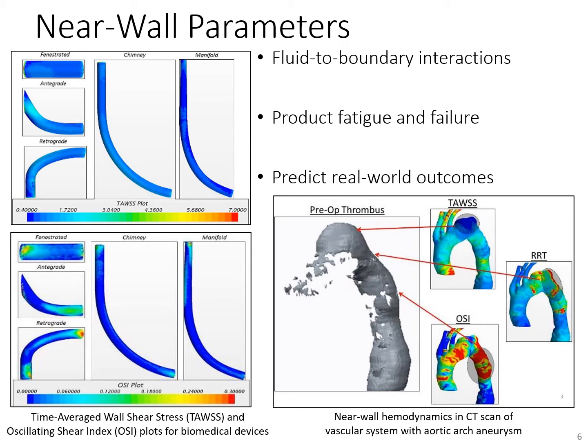Oscillating shear index is a measure of the degree of stagnation and recirculation near the wall boundary. High oscillating shear index shows locations that are especially in danger of atherosclerotic formations occurring, reducing the vessel diameter and increasing the potential for blockages. This research found that long, gradual sweeps of the arterial branches helped keep wall shear stresses at a healthy, moderate range, while also reducing areas of slow oscillating flow to reduce the potential for artery blockage or occlusion.